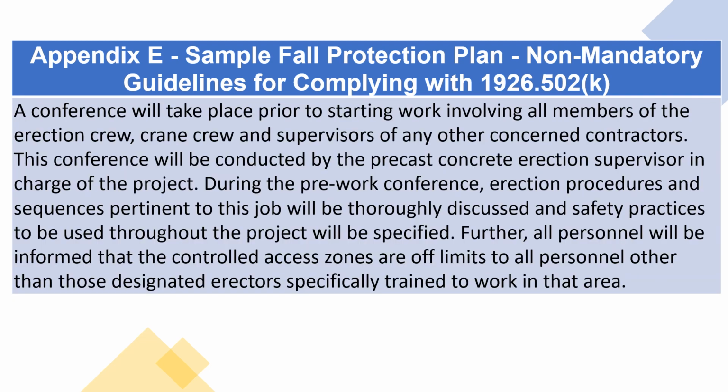A conference will take place prior to starting work involving all members of the erection crew, crane crew, and supervisors of any other concerned contractors. This conference will be conducted by the precast concrete erection supervisor in charge of the project. During the pre-work conference, erection procedures and sequences pertinent to this job will be thoroughly discussed and safety practices to be used throughout the project will be specified. Further, all personnel will be informed that the controlled access zones are off limits to all personnel other than those designated erectors specifically trained to work in that area.